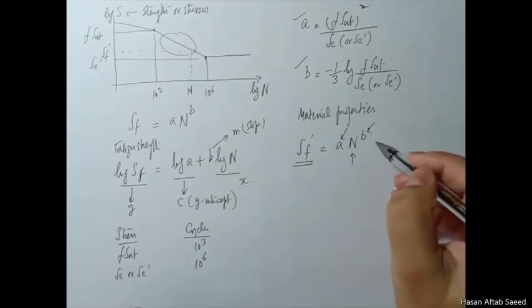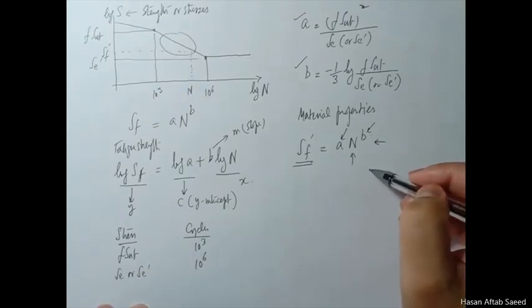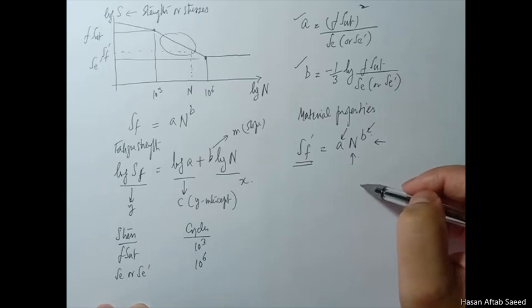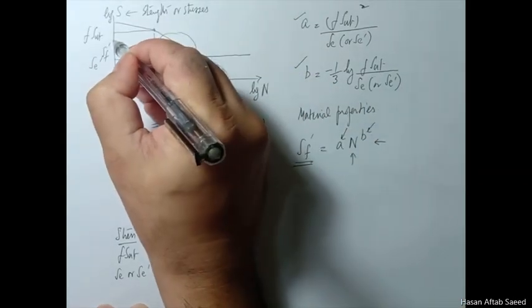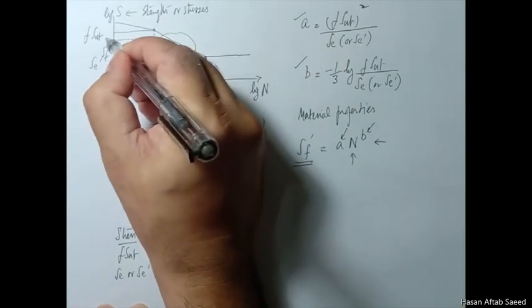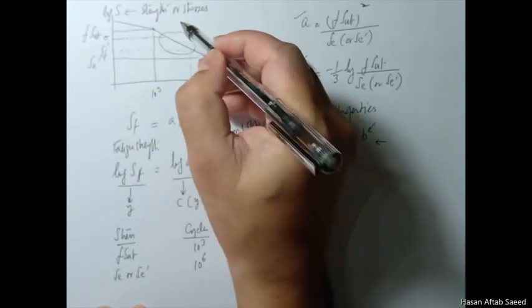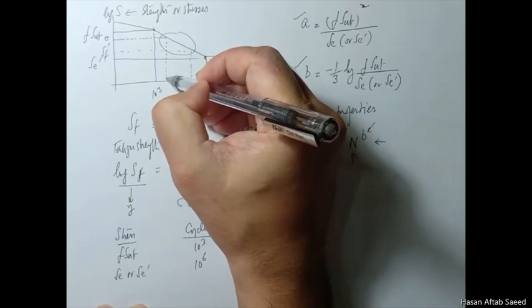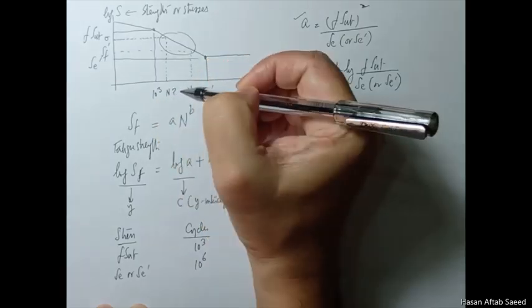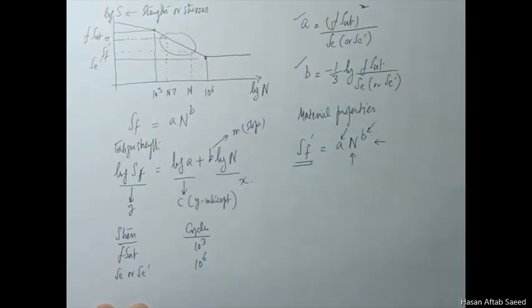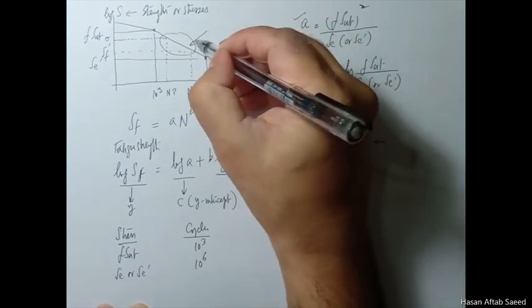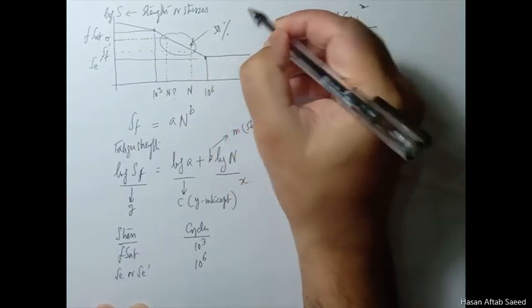one of the solutions. Now conversely, sometimes you know that you are going to apply this much stress amplitude, completely reversed amplitude, and you want to find out for this stress what will be the number of cycles that the component will sustain. And let me remind you here that again, we are talking about 50% reliability here.